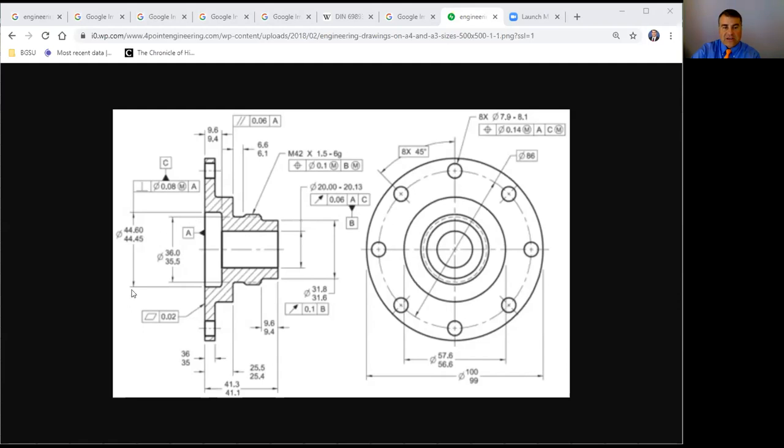So you have these different dimensions, and some matter a lot and some don't. Now, you can monitor and measure every dimension on a product like this, but that's expensive every time you measure something. So usually what companies do is they pick the things that are most critical to the function of the product, and then they'll measure those and chart those.